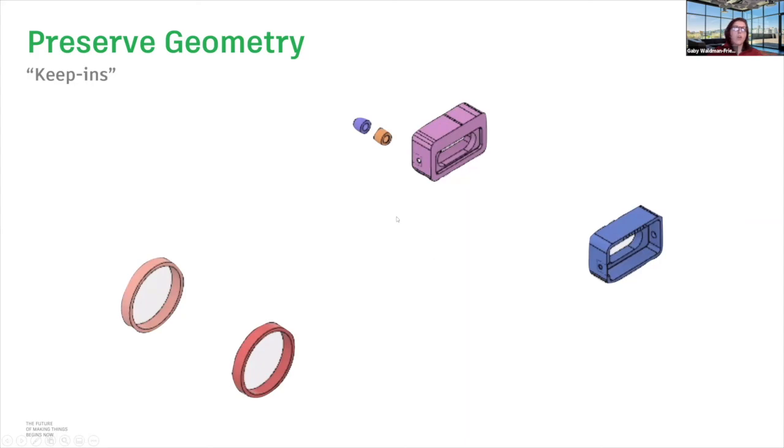So we only want to put preserves into our generative design algorithm, because then it allows the algorithm to create everything in between. We're saying, this is what you're starting with. These things need to be preserved as is, but everything else connecting them, you can optimize. And that's the only necessary piece of geometry that you need to put in.